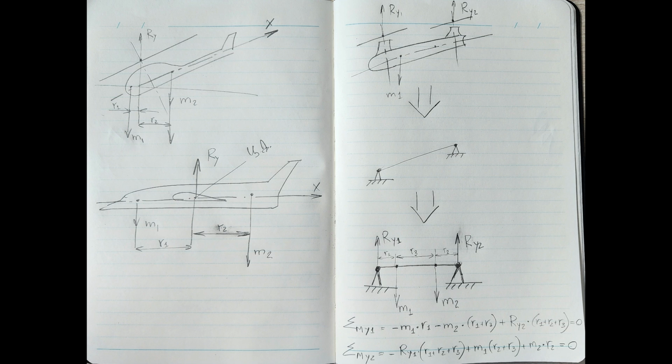Thus, if we have two hypothetical components of mass M1 and M2 applied to points of a beam fixed on hinged supports, then we have nothing more than a classic problem of strength of materials, which almost any engineering specialist has had the good fortune to encounter. Next, we make up the equation of the total moment for each of the supports with one unknown. Based on the results of solving this equation, we can select an air propeller and electric motor for the unmanned aerial vehicle that meets the loading condition.